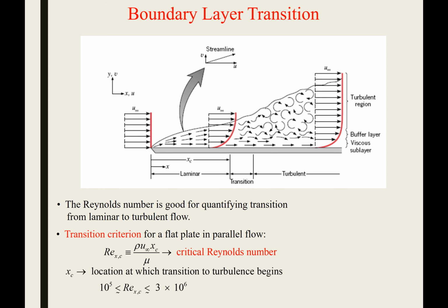So thinking about just fluid flow over a flat plate, we've described a boundary layer, so that fluid will encounter this leading edge. That fluid on the very bottom, quote-unquote, layer of the fluid is going to start grabbing onto the surface of the table. It's going to go slower, which means it's going to slow down. Those viscous forces are going to slow down the layer just above it, and that fluid is going to slow down the layer just above it.